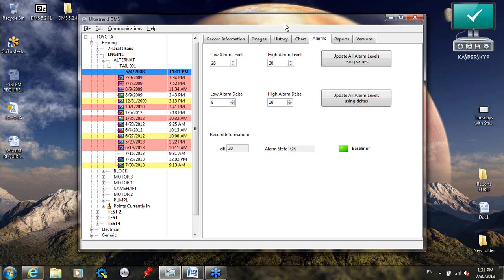So if the bearing does fail and you did your lubrication correctly with ultrasound, you can pretty much take the human factor out of it. You can look at other things that could be destroying your bearing, like maybe a misalignment somewhere within that machine. If you do the lubrication correctly with ultrasound, you can pretty much eliminate the human factor.